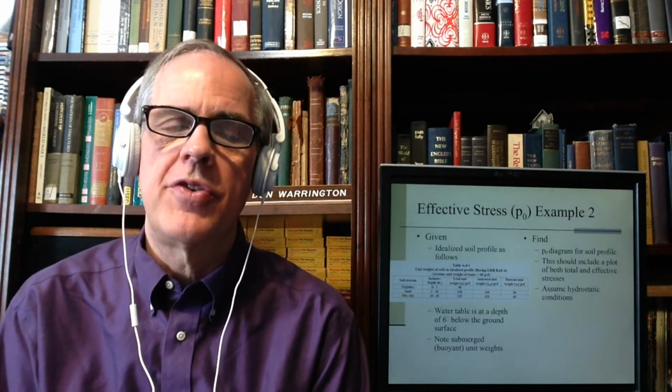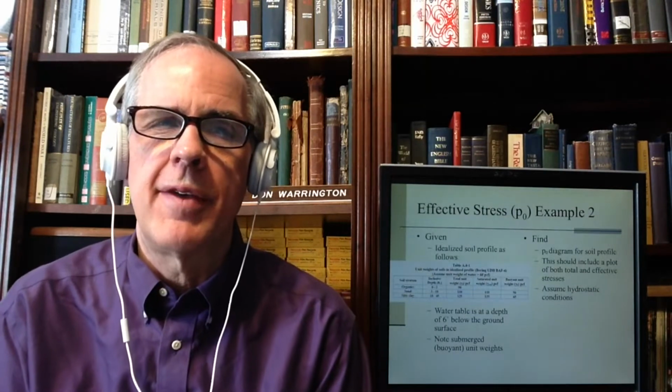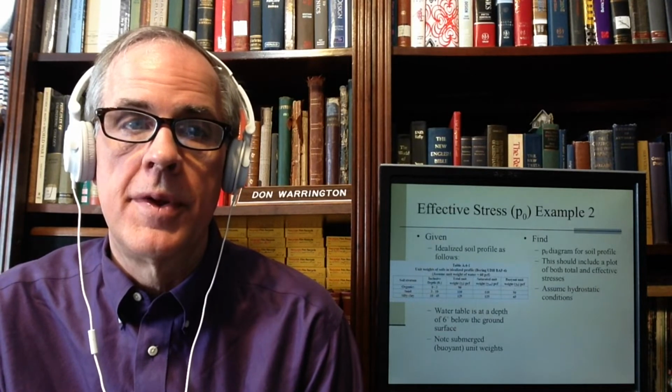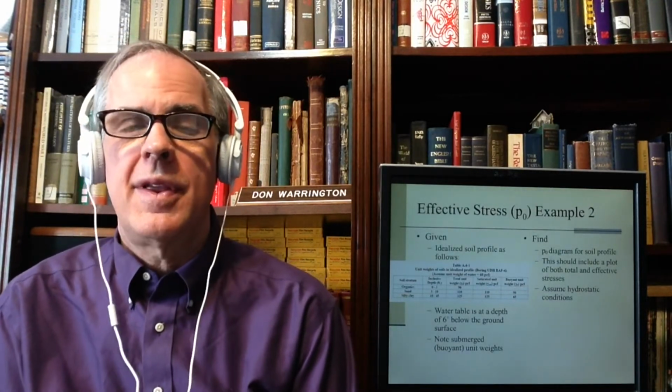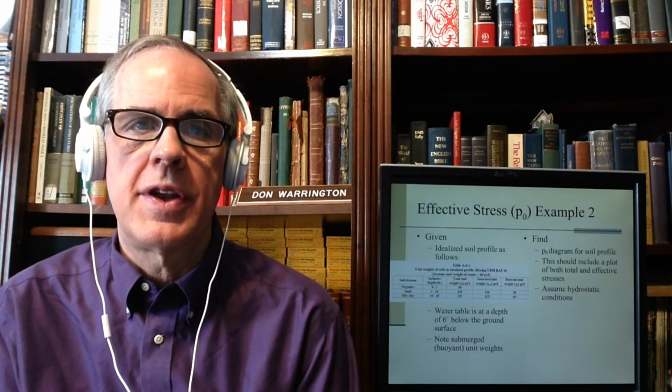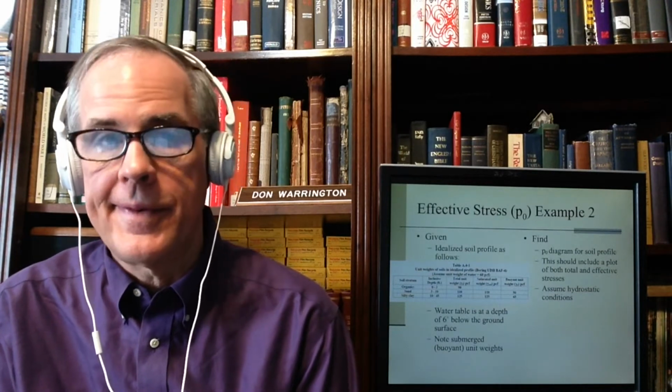Second example, an idealized soil profile. We're going to talk more in foundations about the relationship between most of what the problems you'll have in this course and the next one are idealized profiles. How you translate boring logs, which we talked about a couple lectures back, into idealized soil profiles is one of the interesting parts of geotech. Requires judgment, all that good stuff. But we don't do it. So the idealized soil profile looks like this.